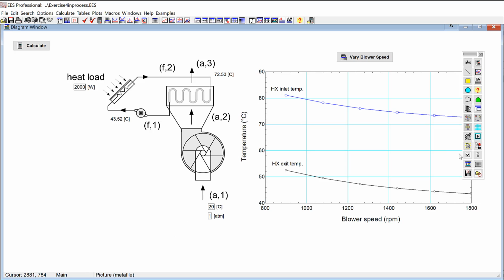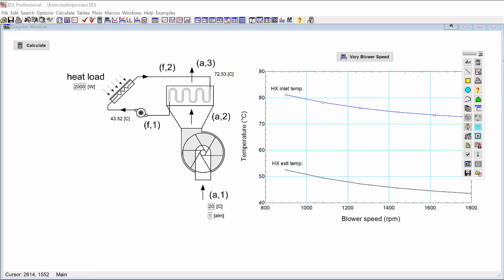So now we're going to make some child diagram windows. And we have to remember how to do that. So here with the main diagram window in development mode, I'm going to define some hot areas. So that's probably the easiest way, so people can just click right on these components. So I want to emphasize where the hot areas are.